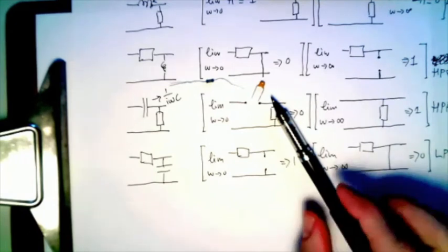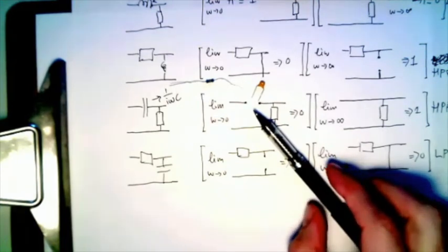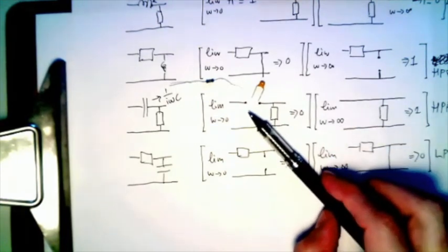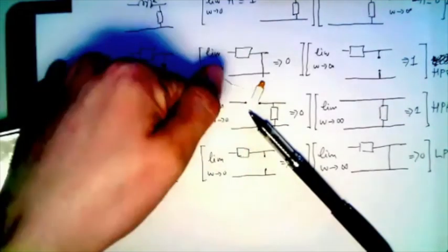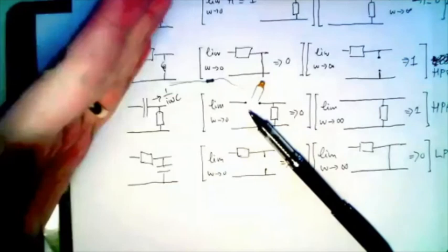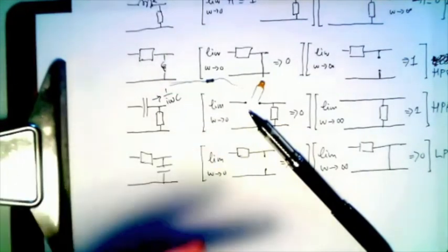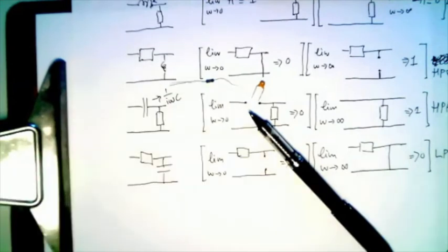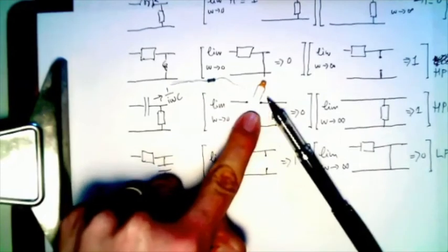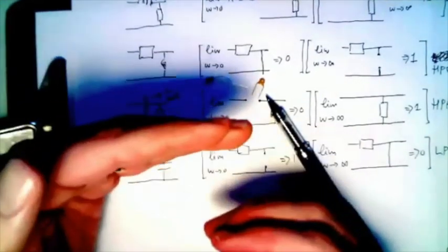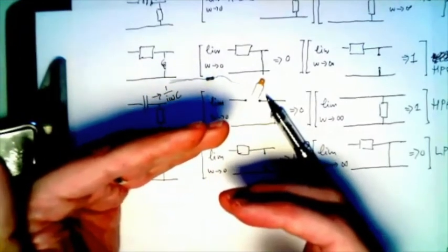So a very famous example was in early telephony, where we still had analog telephones. If you put the receiver on the hook, it would open a contact such that there was no more signal that could run through the telephone. But as you now know, two conductors that are separated by some kind of an insulating gap still constitute a capacitance.